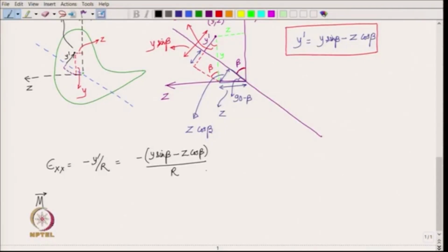Okay. So, the moment in the cross section because of bending stress sigma x x is simply going to be integration over the cross section, then the arm of the point y comma z, that is y j plus z k relative to the centroid, cross product sigma x x i, because the normal stress is along the x axis, and then we plug in the formula.